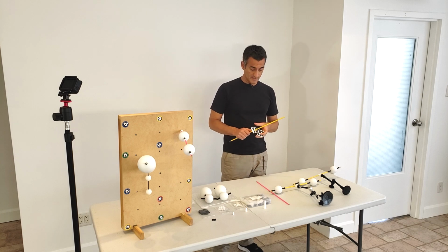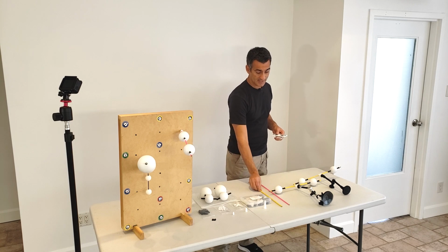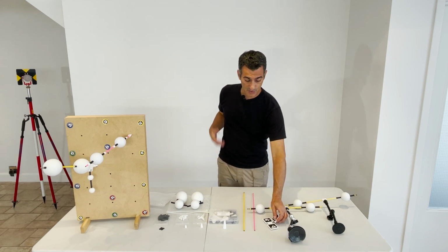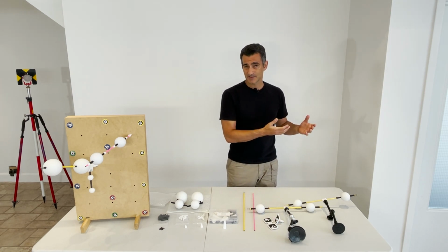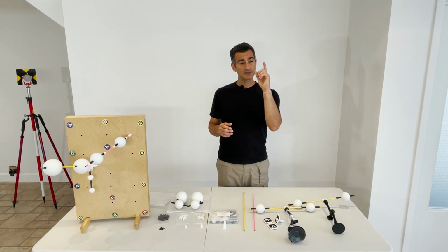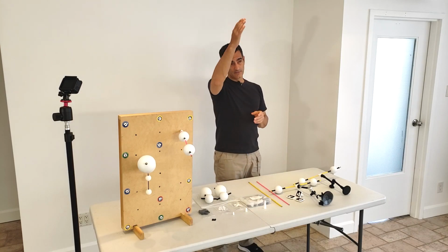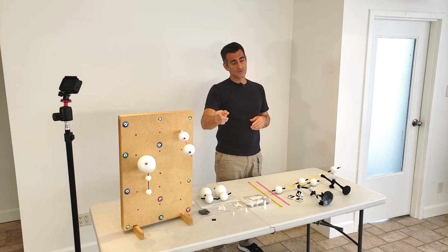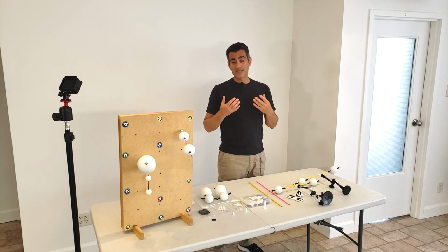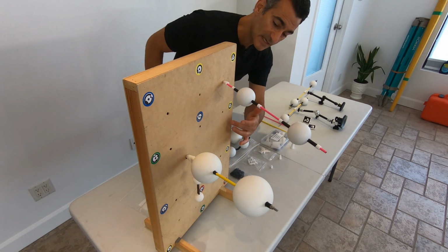So there's a number of different things you can do when it comes to photogrammetry, but one of the downsides of photogrammetry is that it doesn't have an up direction, meaning that it doesn't know which way is truly up. In a device like a laser scanner, you have what's called an inclinometer or some kind of leveling device. It will tell you quite accurately which way is up. So if I want to measure the vertical and the horizontal angles of this trajectory, then I need to know which way is up. So when it comes to photogrammetry, we need to put up targets and we can determine what the angles are relative to a surface.